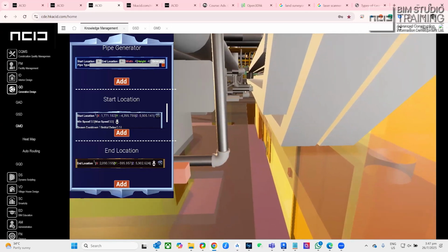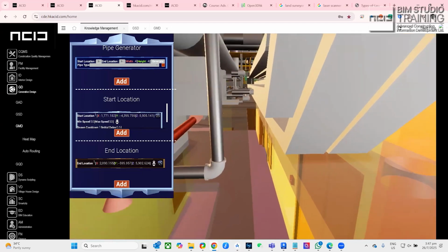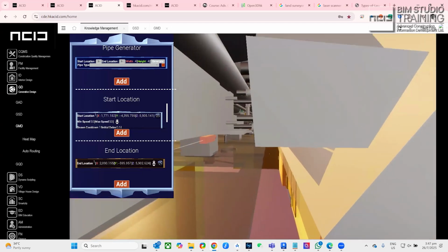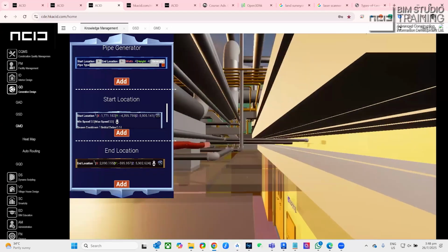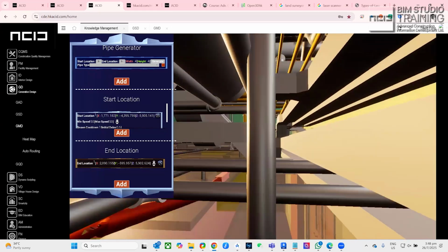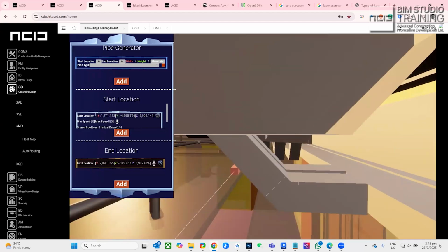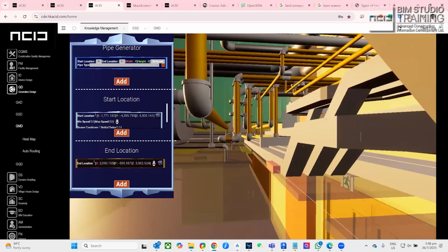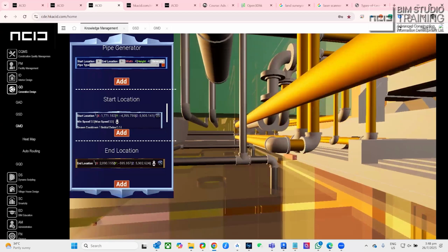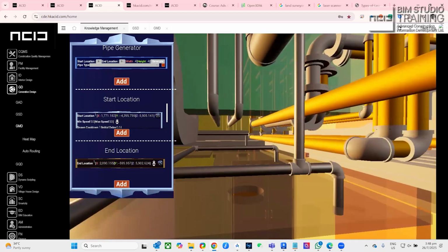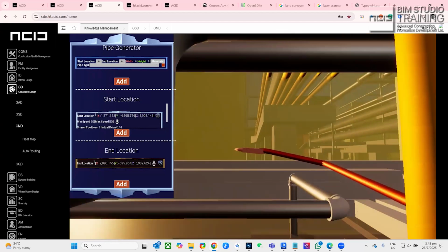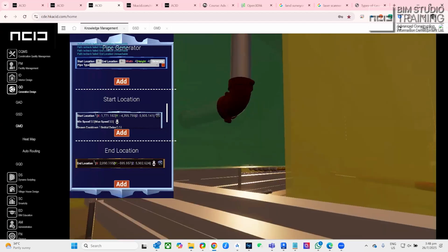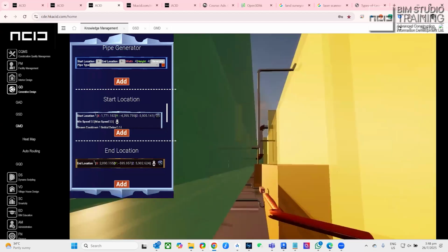So now I'm using a pipe. I'm doing a new pipe for 40 mm. Look, it is detecting from A to B, shortest distance without hitting the object. So this is clash avoidance. It won't have any clash. You don't need to go to clash detection. This is clash avoidance. Why can't we think BIM this way?